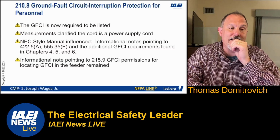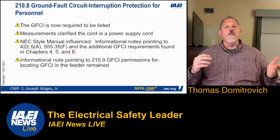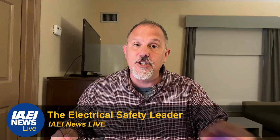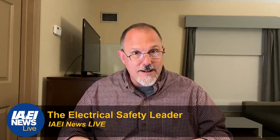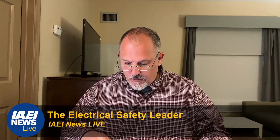At the same time, we had this discovery that there's no listing requirement for ground fault circuit interrupters. Panel 10 was having a discussion and a discovery all to their own in 240.7. 240 is overcurrent protection. 240.7, listing requirements, says the following shall be listed: branch circuit overcurrent protective devices.